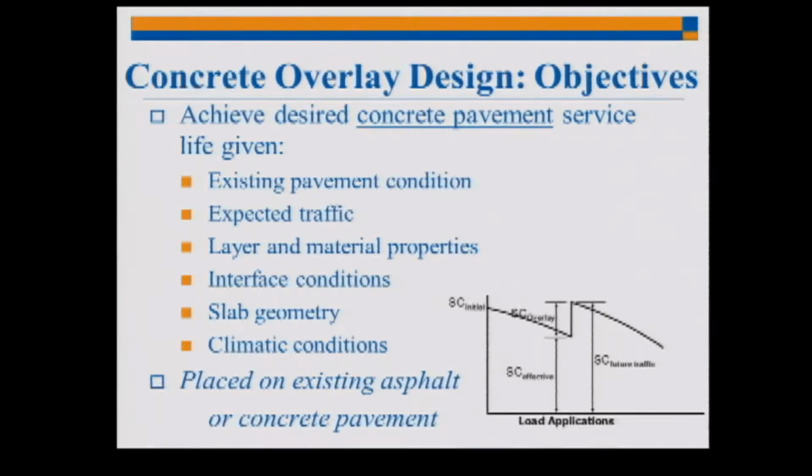So the things you want to think about as you're designing an overlay: we need to know the condition of the roadway. That's very important. A lot of overlays fail because people don't adequately evaluate what they have and whether, when I put an overlay, it will work. The traffic is very important, obviously, especially the amount of trucks, and that goes for any type of pavement design. Another big issue is what type of layers I have and what material properties I could use on my concrete overlay.